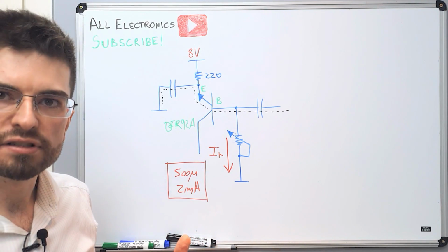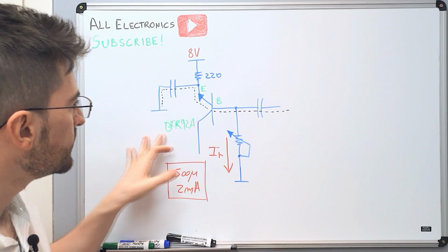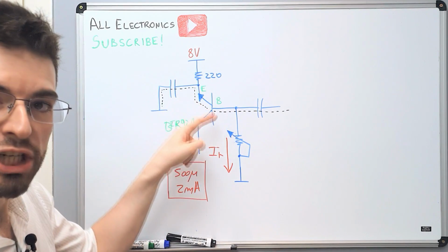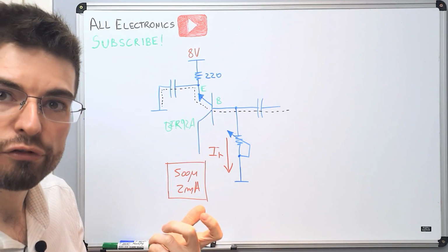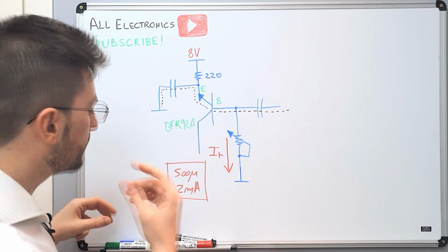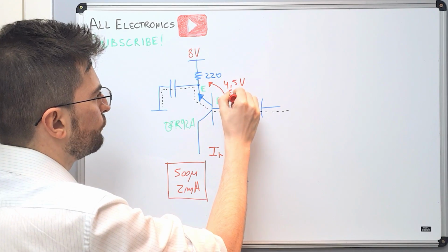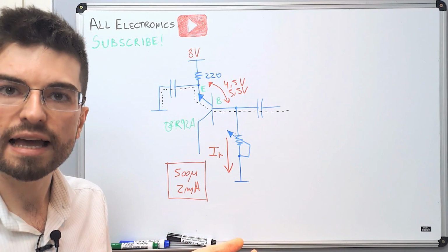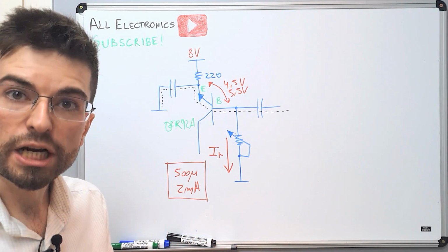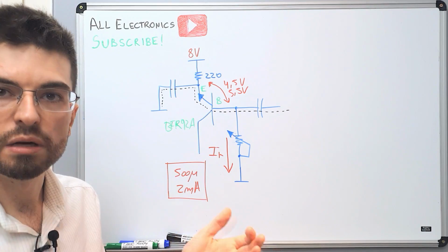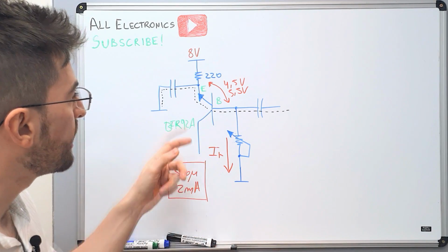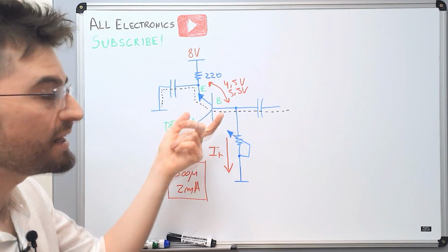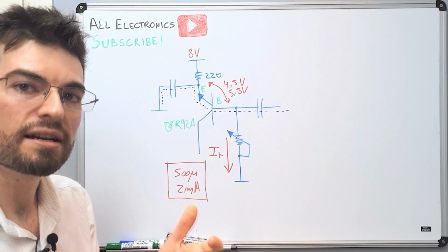For RF transistors like this one here, the reverse breakdown voltage is something like 4.5 to 5.5 volts. So this reverse PN junction is acting in the Zener region by the Zener effect. Some transistors will have a reverse breakdown voltage higher than this, like something near 7 volts.